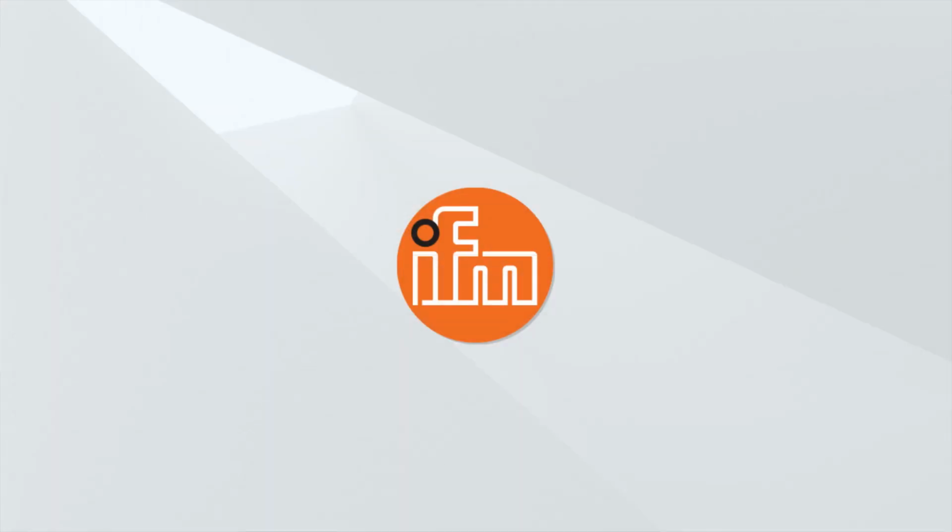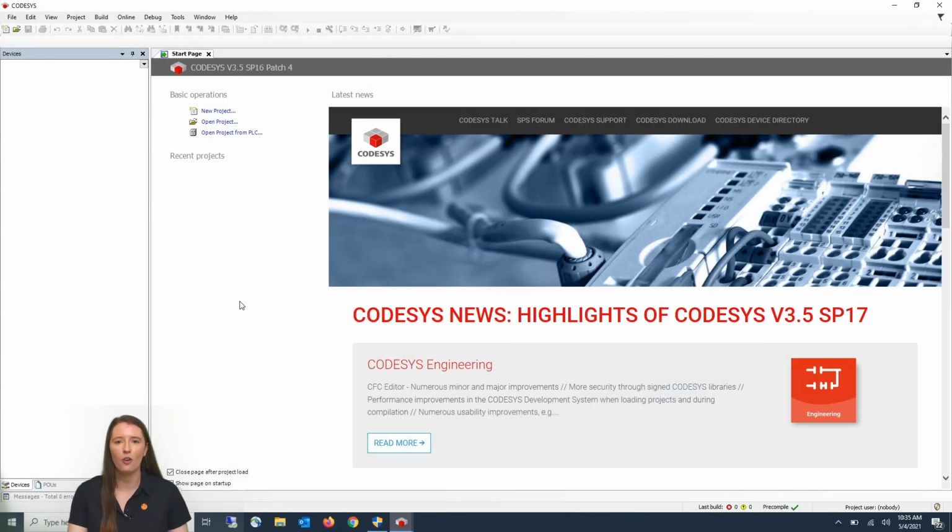In today's video, I'm going to show you how to create a new CODESYS project using our industrial display controllers and IFM IO-Link masters in CODESYS version 3.5 Service Pack 16. So let's get started. Now that you have the CODESYS software opened, you will click on New Project.